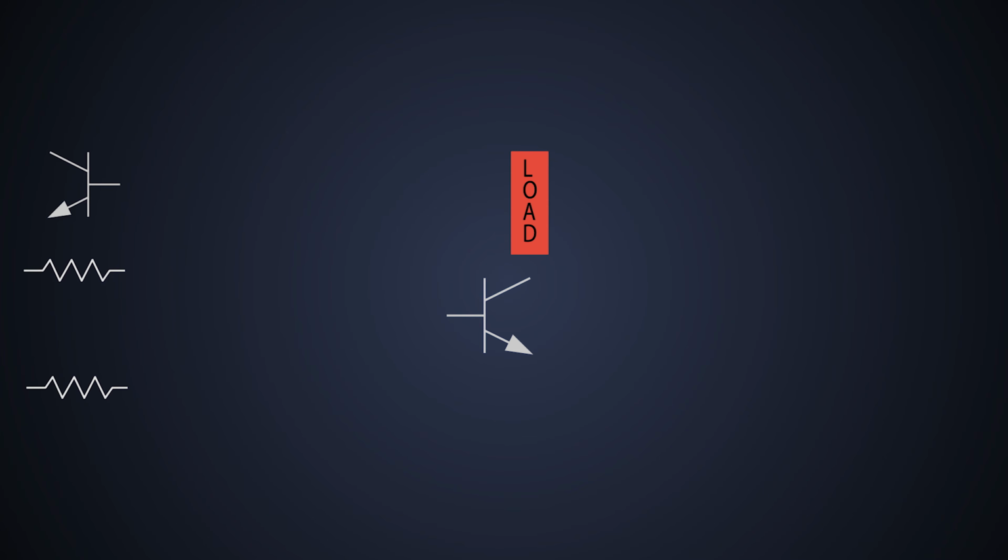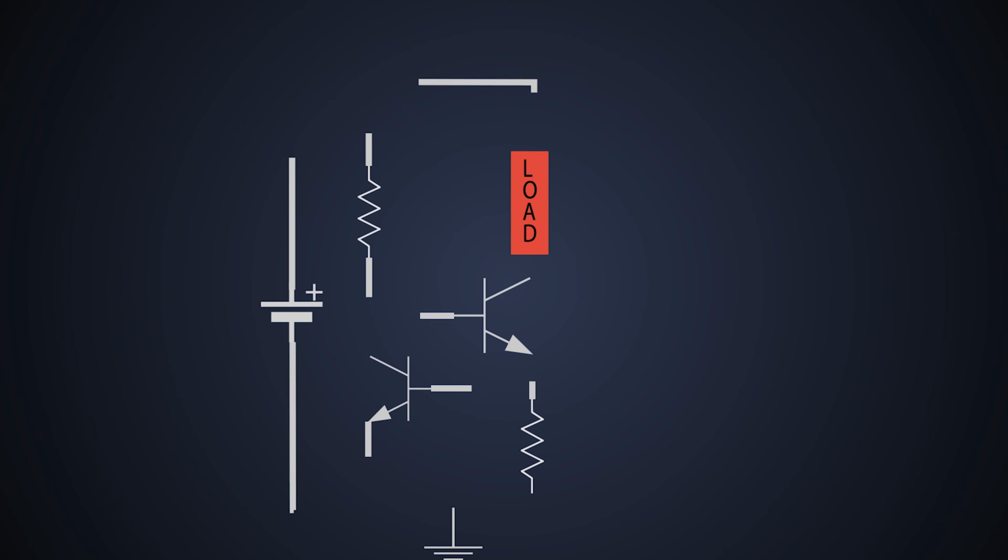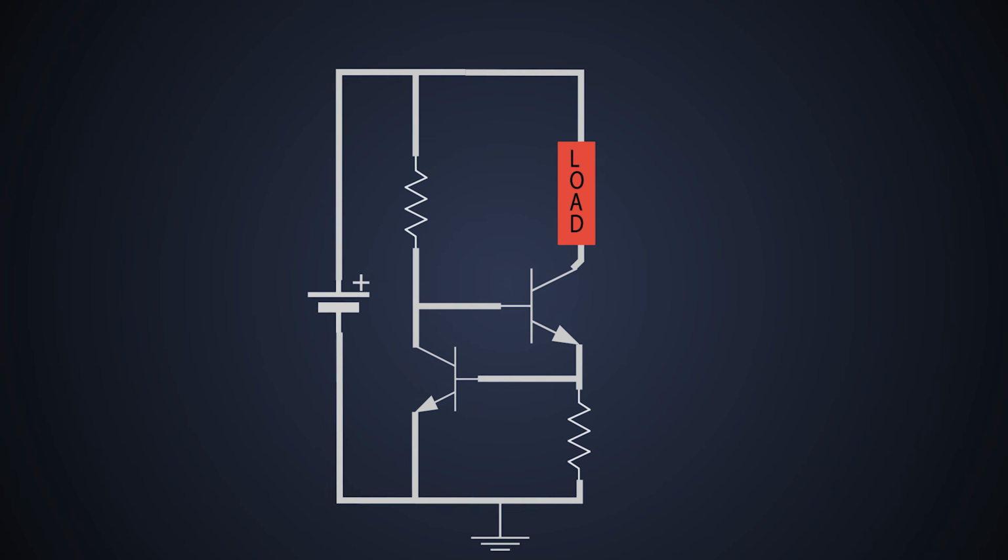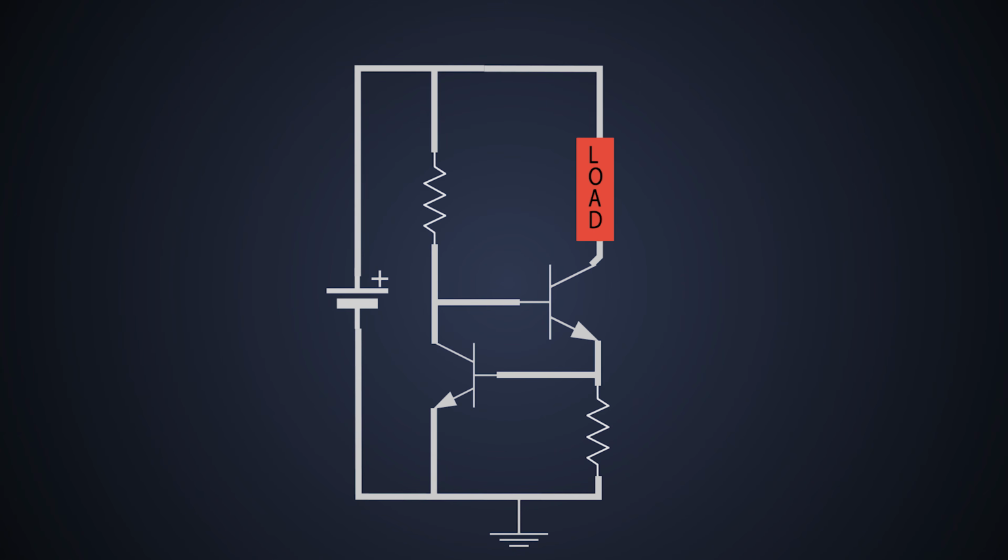The combination of transistors can be done like this. Here we have used BJTs, but we can use MOSFETs as well. Let's name them Q1 and Q2. We will add 2 resistors to this circuit and consider them as R1 and R2. R1 is the current limiting resistor which provides biasing voltage to Q1, and R2 is a very important part of this circuit. The transistor Q2 is the feedback part of this circuit, and R2 is the current sensing resistor. And the load has to be connected between the input source and the collector of Q1.